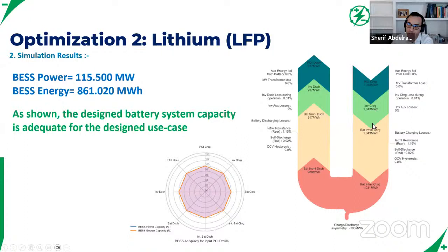That's why we really need to look into where the energy is going. So just for everyone's background, this is the charging portion: charging from the grid, then going through the inverter, then through the battery terminals, and then through basically an ideal battery, and then discharge back into the grid. As you go through these different steps, there are losses here.